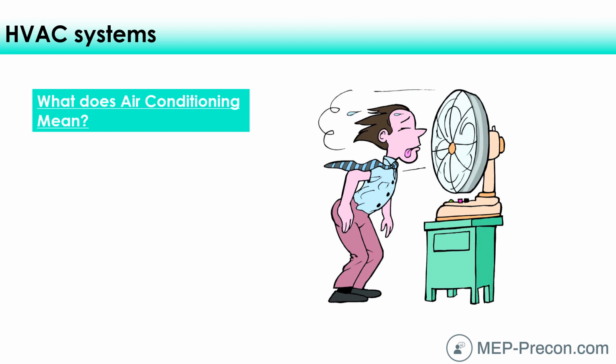So what do we mean by air conditioning? What does air conditioning actually mean? Any thoughts on that? Well, mostly cooling. When people think air conditioning, it's usually synonymous with cooling, but it could be heating. Heating is conditioning of the air, it's heating it up. Could also be humidifying it or dehumidifying it. We could add some humidity with steam, which is probably the most logical way to think about how to add humidity, or we can wring the moisture out through a desiccant dehumidifier or by cooling it with a coil and removing it from a condensate standpoint that way.